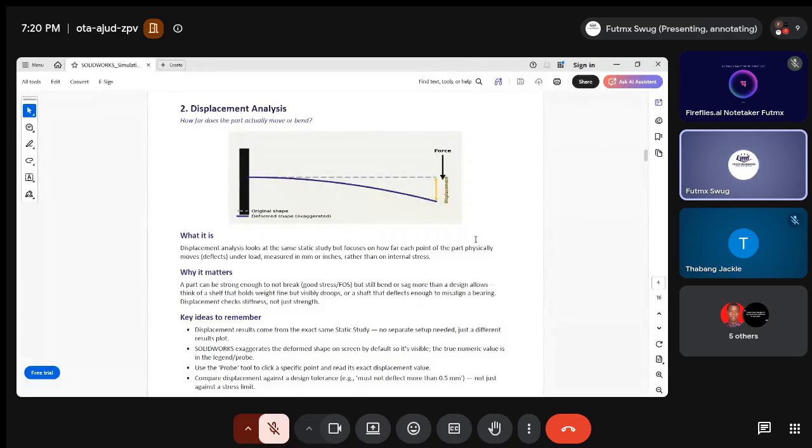And then from your experience, can you allow this level of displacement? Some bridges, after your analysis, you discover that with this amount of load crossing daily, you will have this level of displacement, and it may not be permitted. So for that, you have to improve your trusses, or reduce the load, you understand, so that you can have an efficient design.